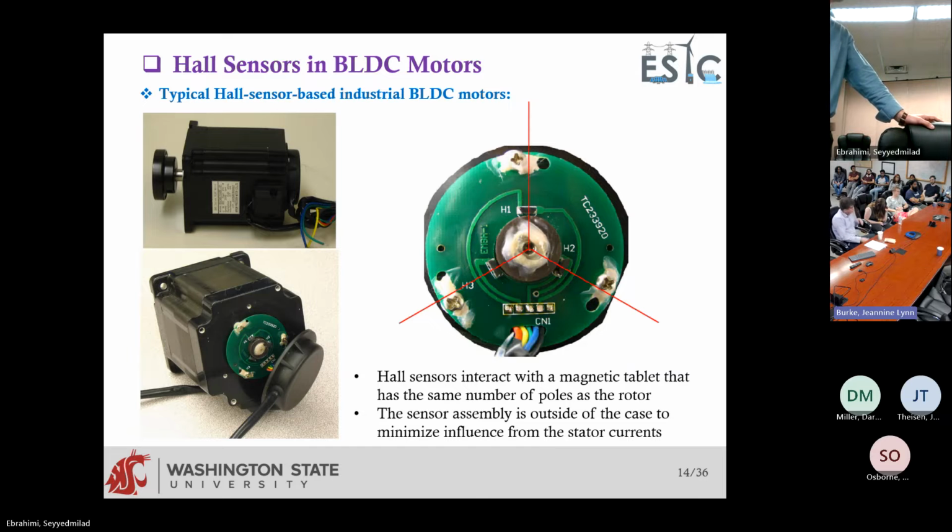So in those cases, do you go with the sensorless control? Or they usually go with sensorless. Instead of Hall sensor, you can also use resolvers or other methods to detect the position of the rotor. That's one cheap way to find the position of the rotor. The more expensive ones use even optical resolvers that try to detect the position very accurately. So this is in everyday applications.